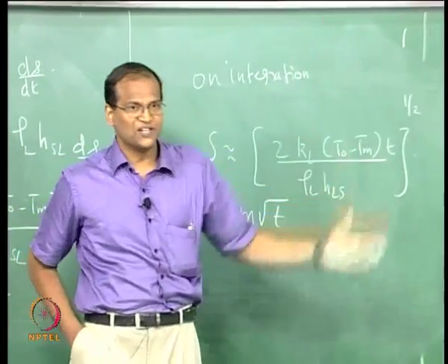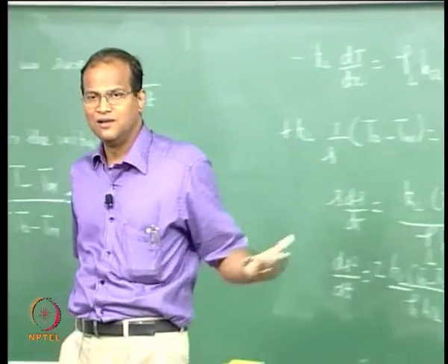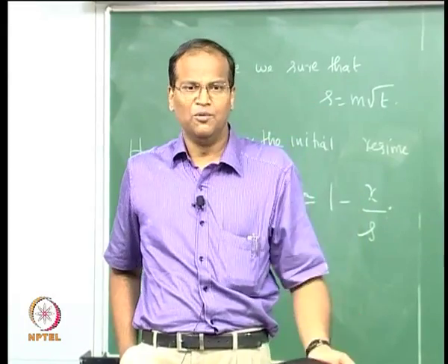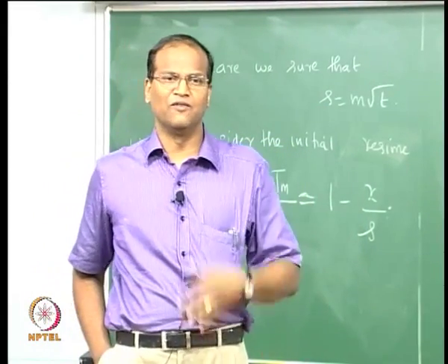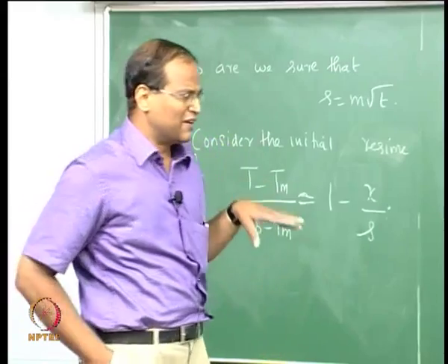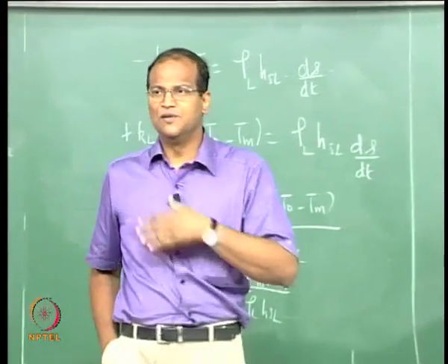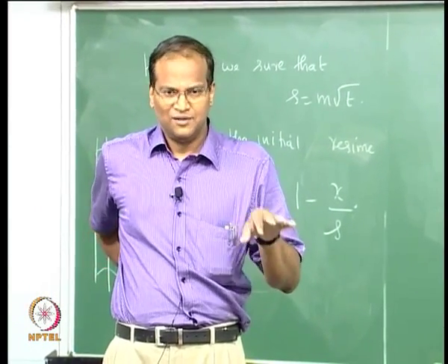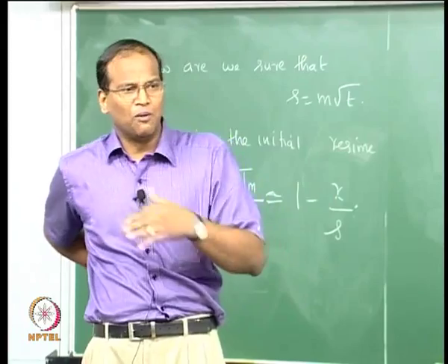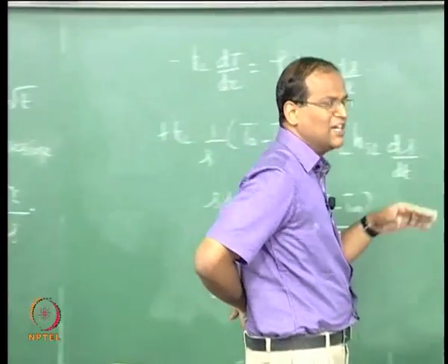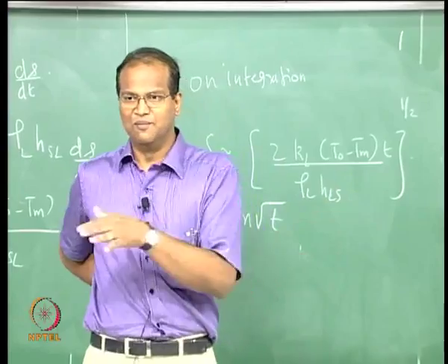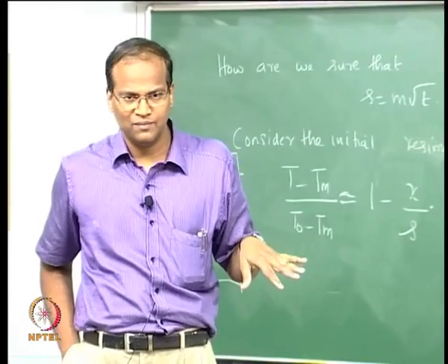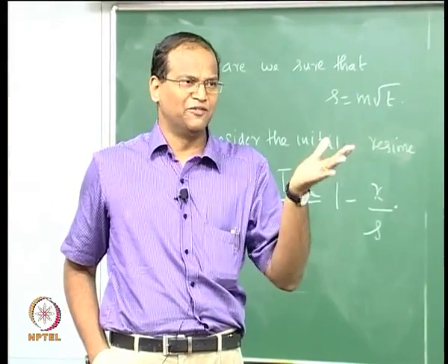Using this hypothesis, if you proceed further, you will finally get a solution where you can solve for mu. It is highly complicated in mu. Therefore, given the mu, you can work out the Stefan number and then find out how much heating is required. But the Stefan problem is infinitesimally slow heating. The Stefan problem and Neumann problem are different, because in the Stefan problem the body is initially at a temperature equal to Tm everywhere, but in the Neumann problem you can have a temperature which is different from Tm. These are the basic differences.